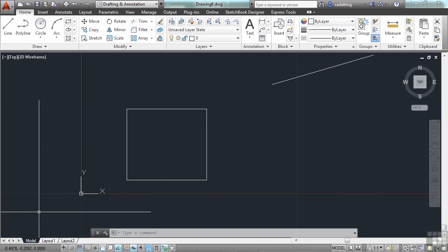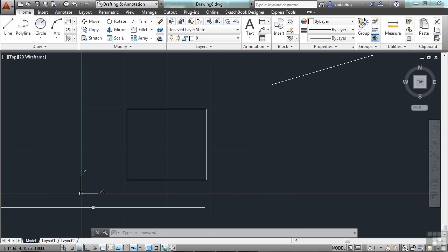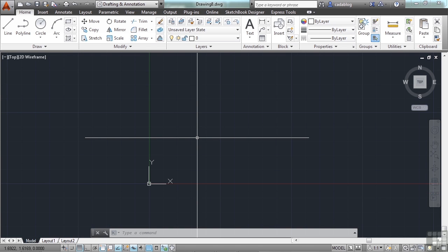When I move over here to the left and lower of the UCS icon, you can see my coordinates are negative. To the top right, they're positive. And the X and Y become positive and negative accordingly. You can draw objects to distances, or you can draw them to static coordinate points. For example, let's draw a line that starts at the origin and goes to coordinate 3, 4.